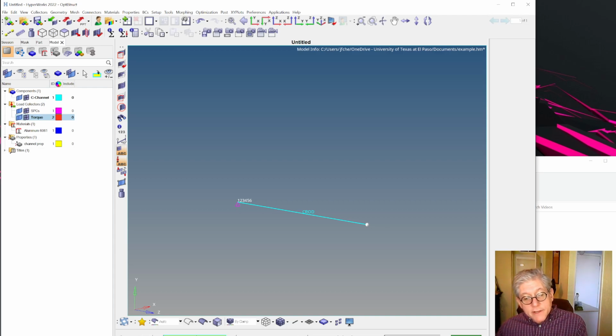So one of the ways is just picking an axis. And for us, that's the easiest, right? So it's going to be around the x-axis. So I'm just going to click x-axis. And so now you can see this is a moment around, I'm sorry, I said x-axis. The z-axis. I click it. What I say doesn't normally mean what I do. Okay, so the z-axis, right? So this is going to put the 1,000 moment around the z-axis. It's going to go in a right-handed sense around here.